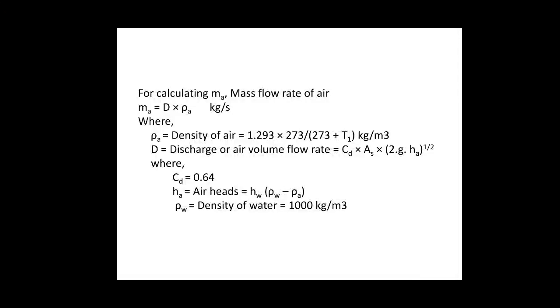From here, we can calculate the mass flow rate. We put that value in the formula for heat gained by the air, and we put that heat into the heat transfer coefficient formula, and we will get the heat transfer coefficient of the test plate.